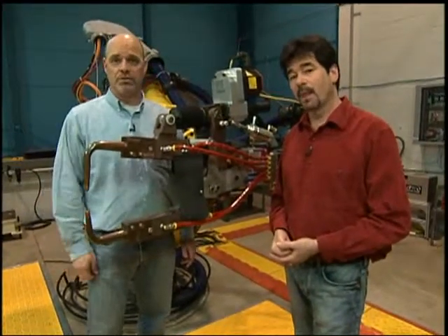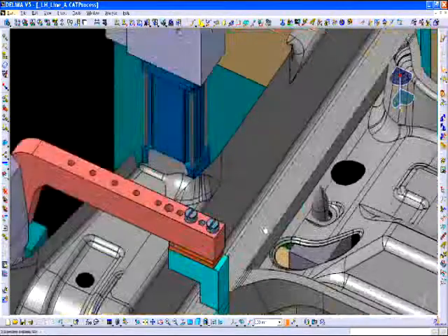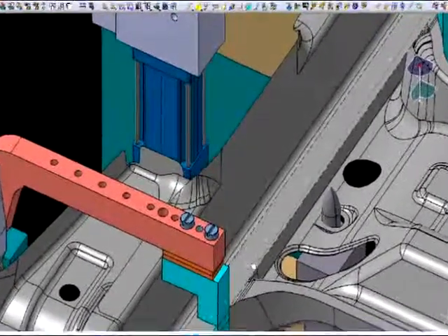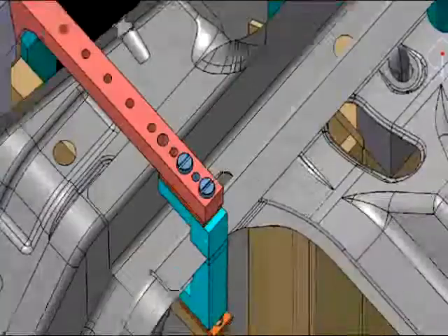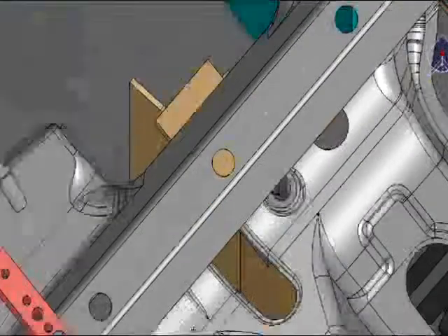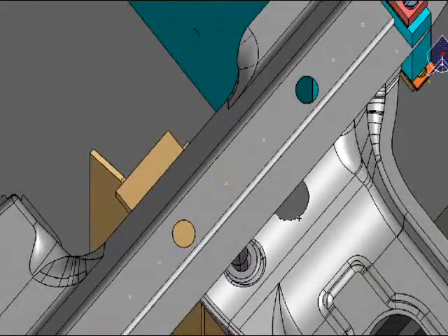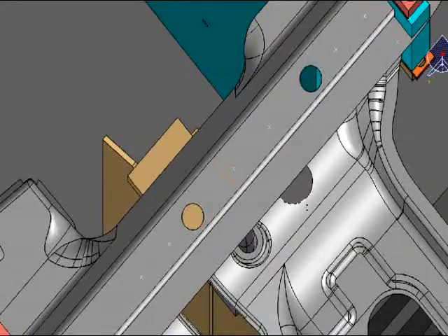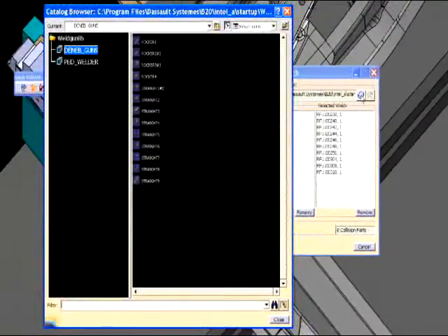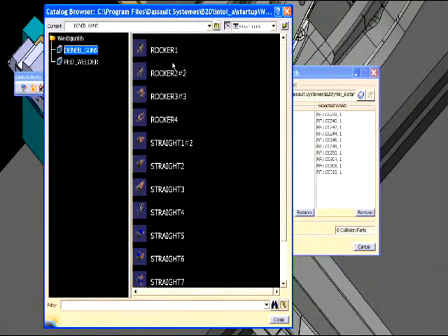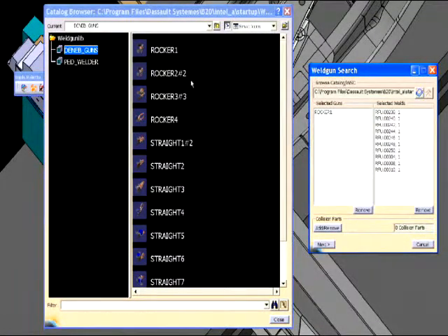virtually impossible. Companies are using simulation software to assign thousands of spot welds to the hundreds of robots that they have in production. That's because they can simulate the weld guns on each of the welds automatically. Automotive companies maintain a 3D inventory of weld guns in a library and use software simulation tools to search for all the weld gun solutions that will satisfy any weld or group of welds on the car.